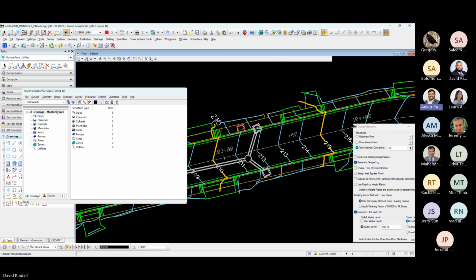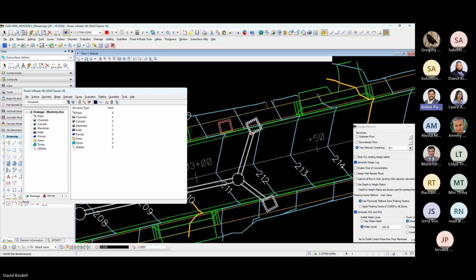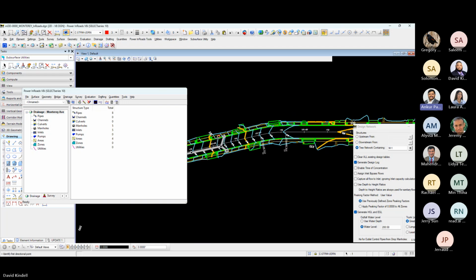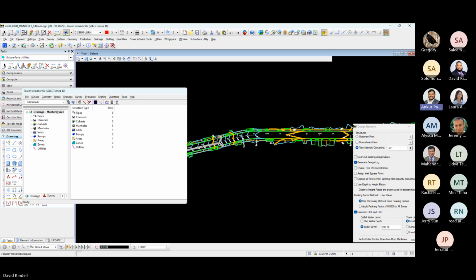It needs to be on the line, because this is not what's displayed in the plan, right? Whatever is in our MDD really needs to match super accurately, because like Jerry is saying, the length of this pipe is what's going to be in the pipe schedule, what's going to end up in the cost estimate, and what's going to change the slope of the pipe as well. So we really need to make sure we match what's in MicroStation in the MDD file.